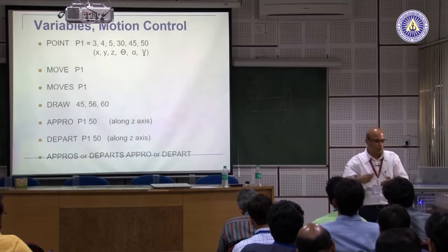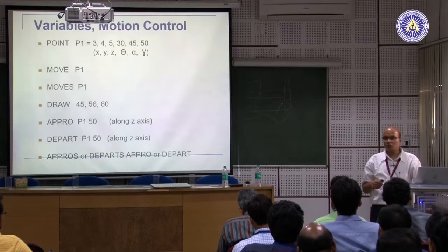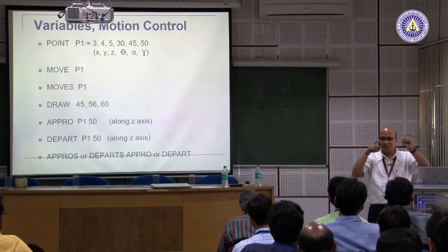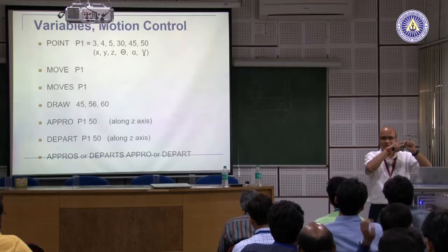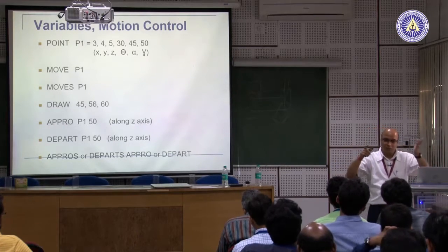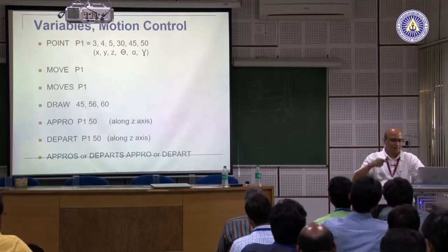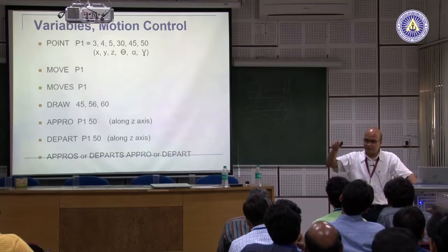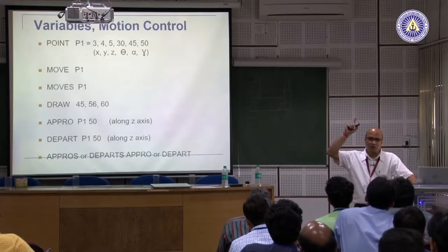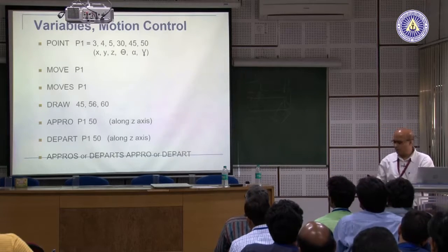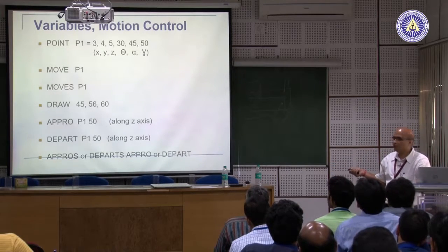Now, why is this not preferred? Because to move straight means you must have infinite points on that straight line, and you have to go to those infinite points to be able to keep a straight line. So that means excessive computation, and also sometimes it may not be possible, and excessive energy usage. So the robot will become extremely slow, energy requirement will go up, and all kinds of things happen. So normally we move in a straight line only when required, not otherwise.